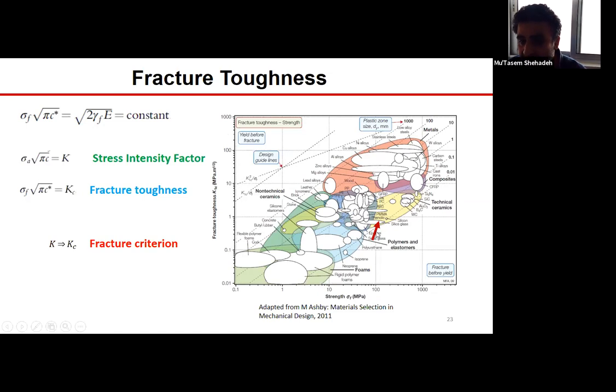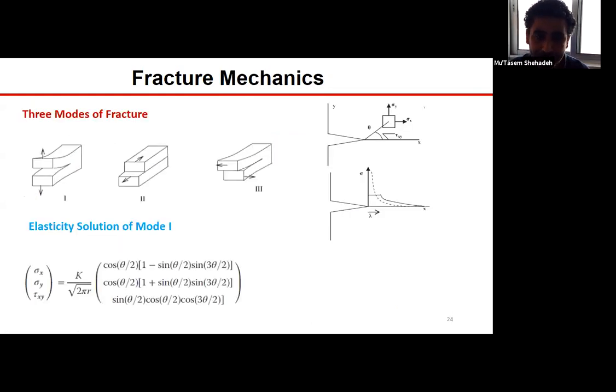And that's, again, the main thing here, that these materials are very, very brittle because their ability to absorb external loads, energy, is not that big. The energy is, in fact, dissipated in the process of crack propagation, as opposed to, let's say, a process of plastic deformation, which is the case in metallic materials and also in polymers.